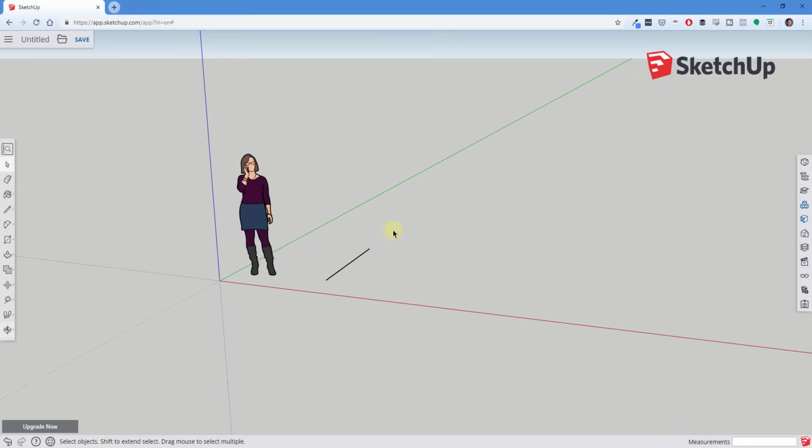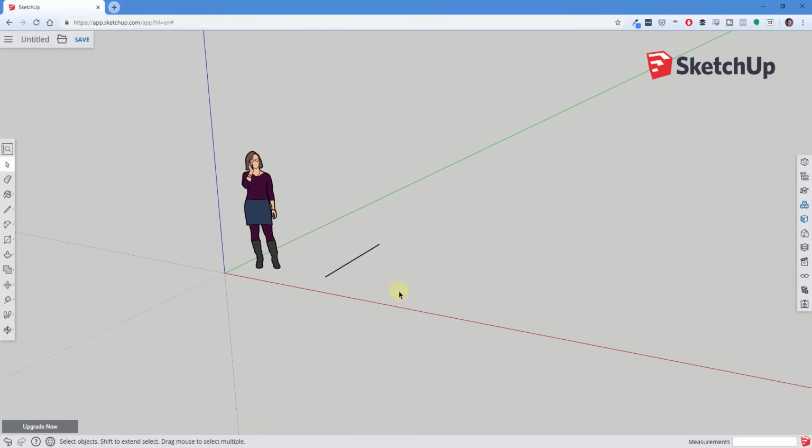And so now that we've gone through and talked about navigation and your toolbars and everything else, now let's talk about drawing inside of SketchUp. And so drawing is fairly simple. You just activate a tool by either clicking on it or typing in a keyboard shortcut, and I usually recommend you use keyboard shortcuts because they're a lot faster, and then you just follow the instructions. So in this case, this says to select my start point to draw a line.